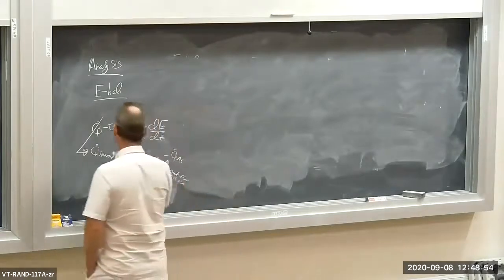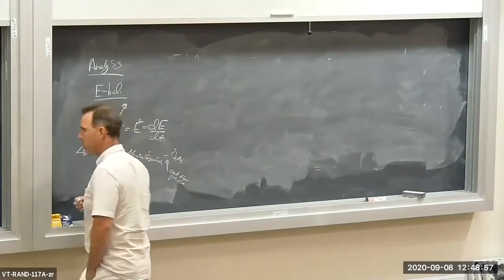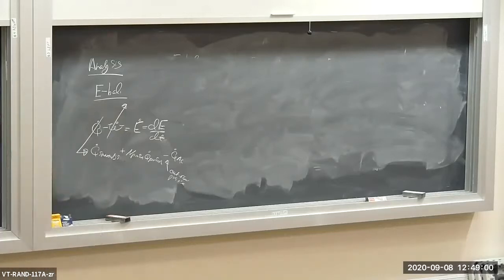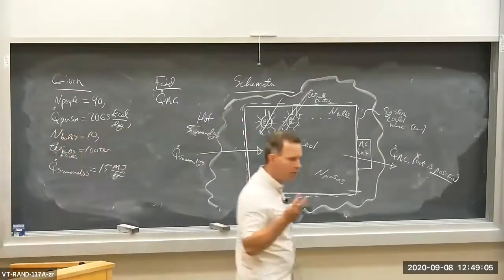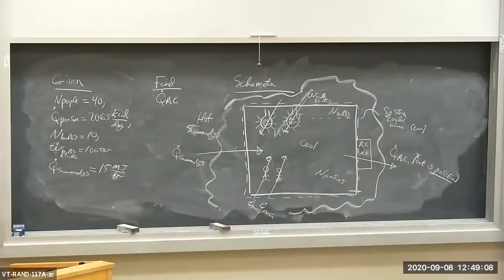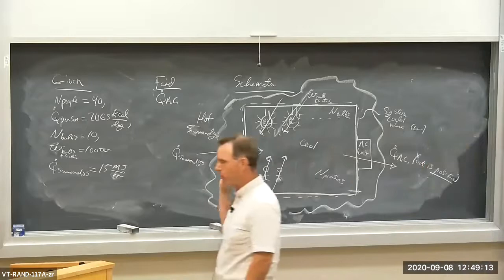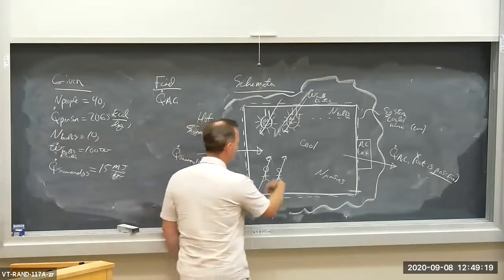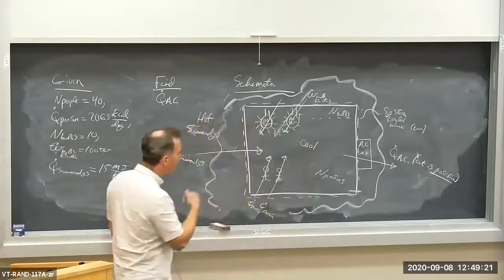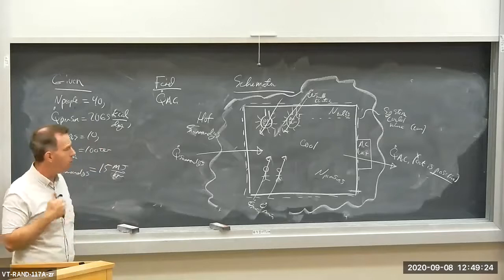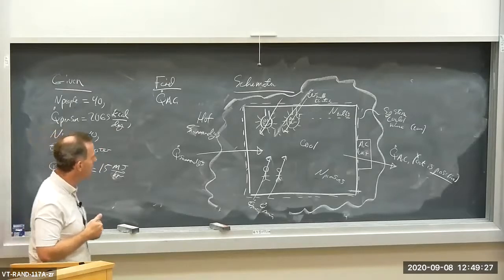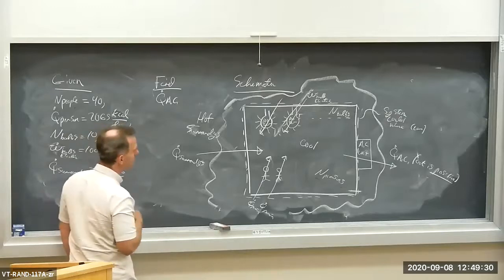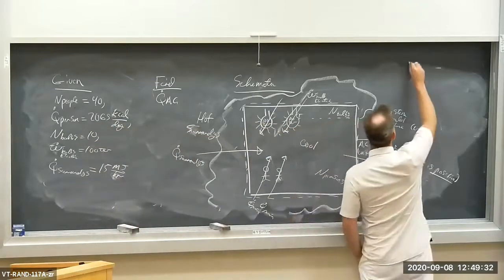What about the work term, W dot? What kind of work is going on in this problem? Well, remember there are 3 different forms of work. There's boundary work, electric work, and shaft work. There's actually a 4th kind of work, but we'll talk about that later. As far as we're concerned, there are 3 kinds of work. There's no shaft work going on. There's no propellers in here. There's nothing stirring the air around that I can see, so I'm going to assume that there's no shaft work. By the way, it's getting a little tight here. I'm going to write my assumptions here.